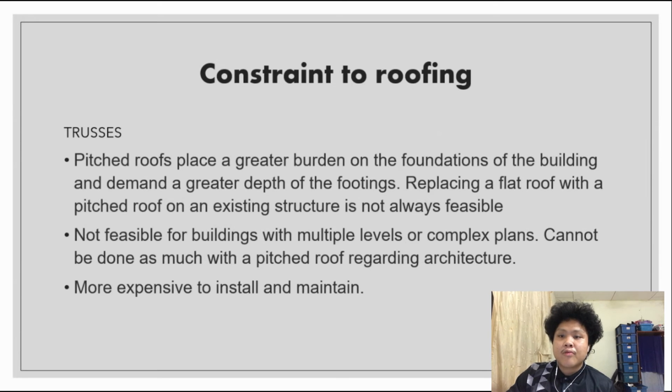Replacing a flat roof with a pitched roof on an existing structure is not always feasible. It is not feasible for buildings with multiple levels or complex plans, and less can be done architecturally with a pitched roof. And lastly, it is more expensive to install and maintain.